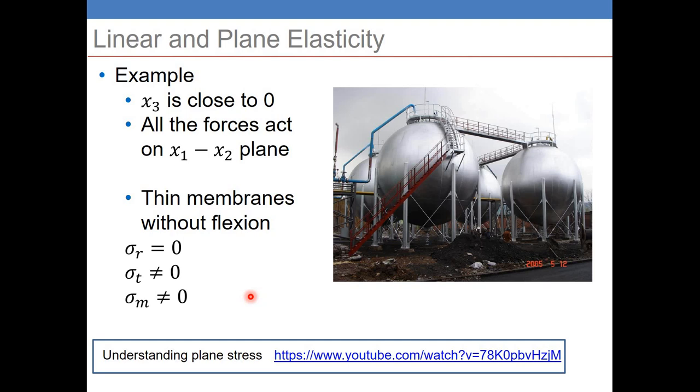Now, to summarize, plane stress and plane strain are both widely used in engineering. For plane strain, if I want to go from a 3D strain to a 2D strain, I need to have a very thick plate, and I don't need to have any force along the thickness. For plane stress, the one that we just studied, I need to have a thin plate, and also I don't need to have any force acting over the thickness. I can go from a 3D state of stress to a 2D state of stress by putting to 0 all the stresses in the plane normal to the thickness. So that's to summarize.